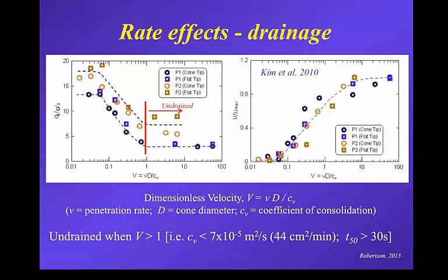So the complex soil behavior makes the theories less than perfect. Most theories assume some simple stress-strain model, either elastic, perfectly plastic, or some simple nonlinear stress-strain curve, for example, like Cam clay, whereas real soil response is a lot more complex, highly nonlinear, often strain softening where soils are sensitive, and often rate and stress path dependent. And of course, there is the complex loading around the cone, and the unloading around the shoulder that causes big differences between pore pressures on the face of the cone and just behind the cone.